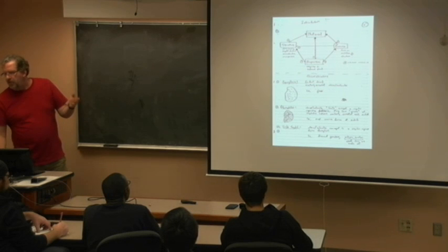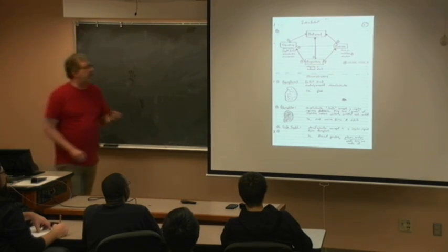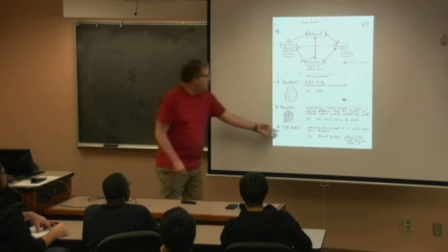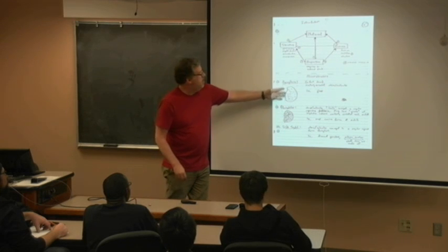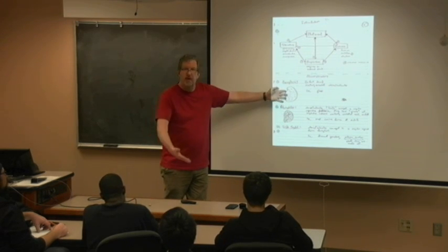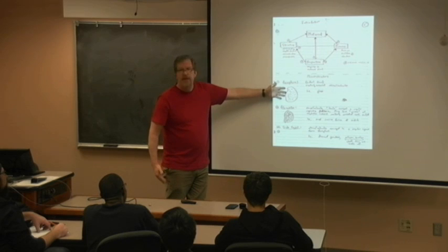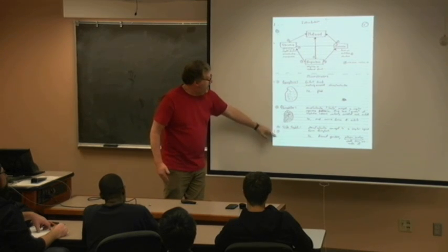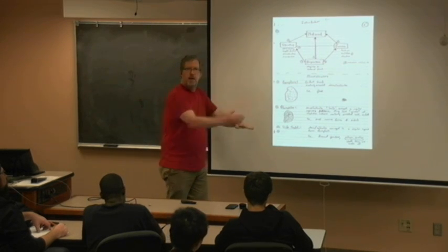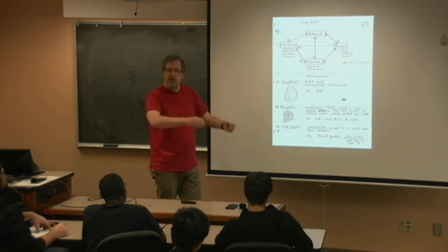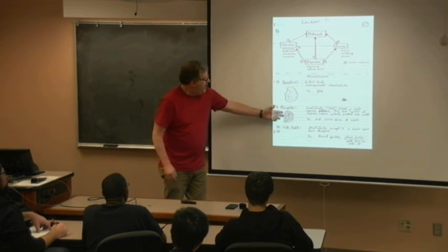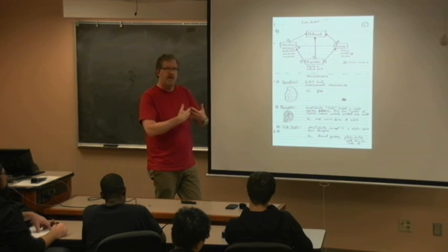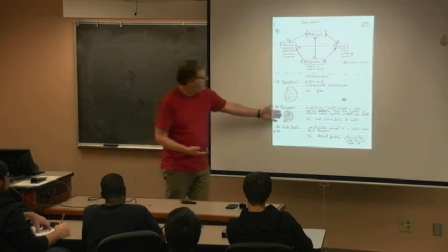So you have the materials properties where you can have single crystal, the polycrystal, and amorphous. And clearly now, as we've studied mobility, you can see how these might attenuate the mobility. Single crystal is going to be nice and perfect, so the electrons or holes are going to zip right through. And you can see the polycrystalline is going to be scattering and so forth. So obviously that's less desired.